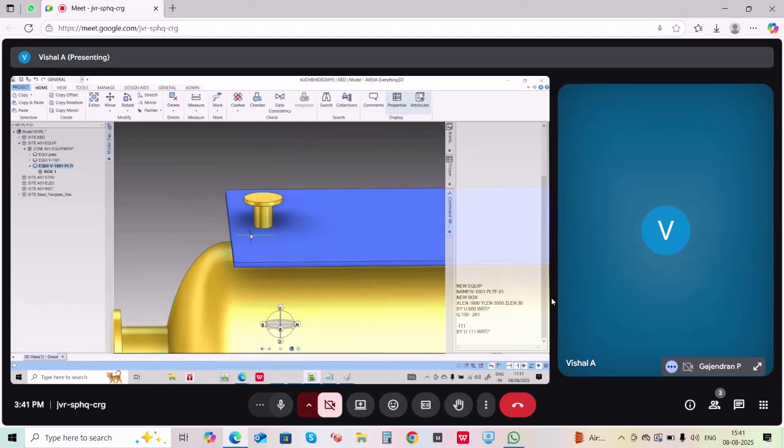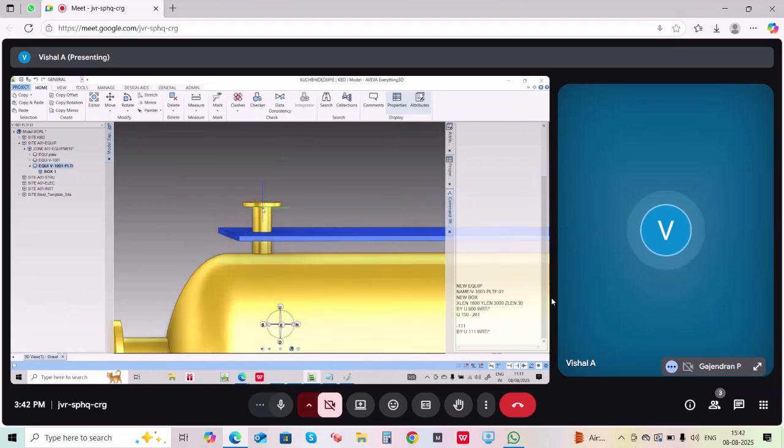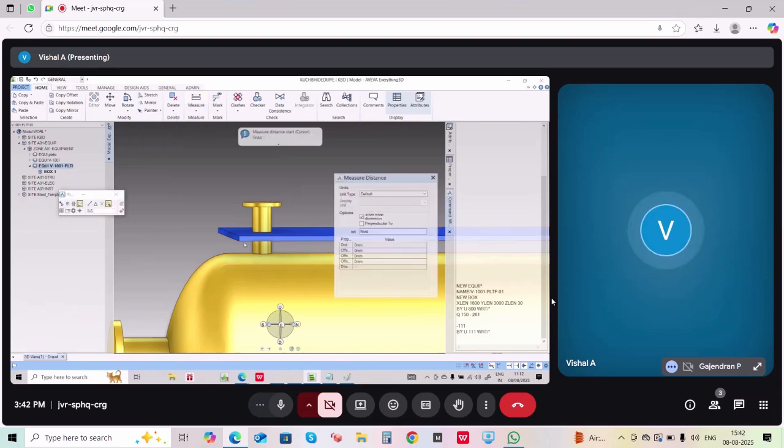Okay, cool. So why am I putting this 150 mm gap? Because there will be bolts, and when you try to unscrew the bolts and nuts, your hand will be at the bottom of this, and your hand should not scratch against the grating. So that's why we have a clearance. Now the clearance needed at the bottom of this is also near about 150 mm for the safer side, so you have to cross check. Take the bottom of this and the top of this. How much is it? It's 96 only. Max to max we can go for 100 mm.